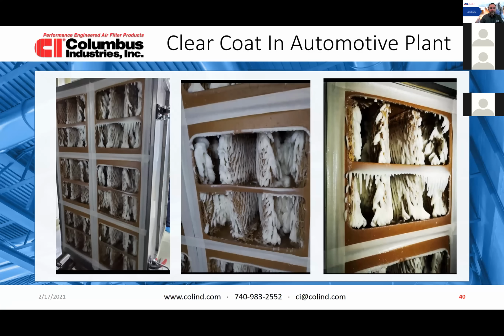In the automotive industry, this is a sample of a clear coat cart. As you know, some lines now have a cart that has 6 filters or 8 filters. It depends on the manufacturer. And it gives you the flexibility of having a cart ready, taped and ready to go. You take out one, you put the other one back in without stopping the line.